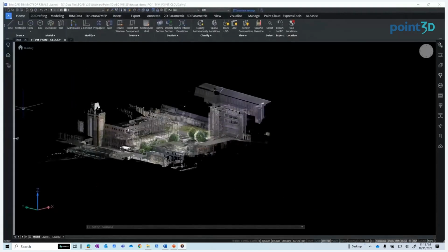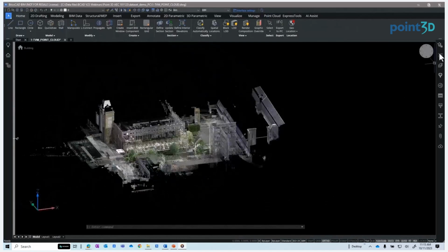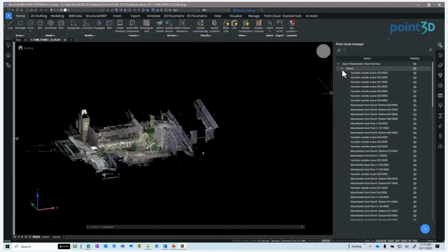Now, here's our second example, and this is that HSPC file format. This allows for the storage of metadata per point. This point classification is done using Leica's Cyclone 3DR software before the point cloud is exported out. Then, when an HSPC file that's been classified is pre-processed in BricsCAD, those classifications are visible and can be managed within the Point Cloud Manager panel here. We see the displays of the scans, the regions, and classes available.